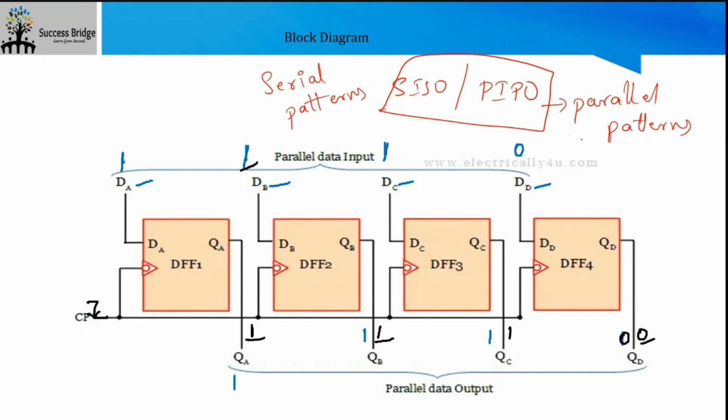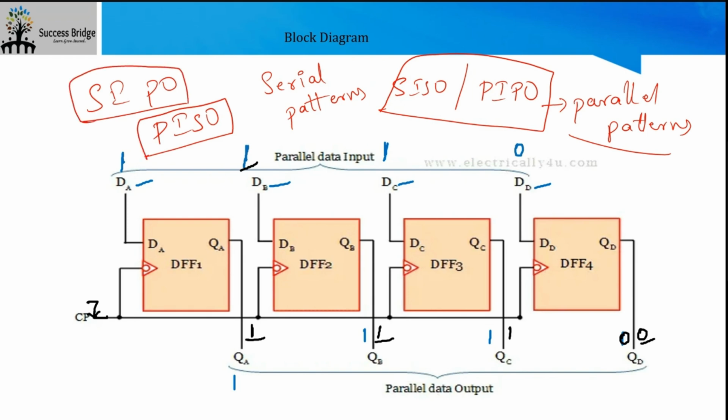When we want to debug certain serial patterns or parallel patterns, we will go with serial in, parallel out, or parallel in, serial out. So this is the mechanism supported by the tool to produce the required patterns, but there will not be any design logic inserted in the design because, as I said, each flop will have one mux internally, the scan mux.